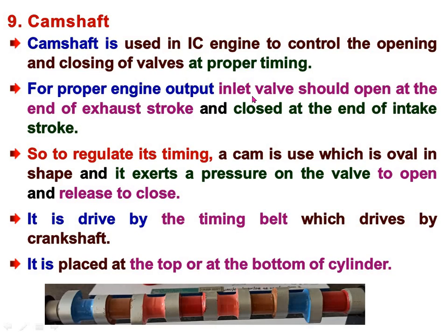For proper engine output, the inlet valve should open at the end of the exhaust stroke and close at the end of the intake stroke. It means for taking in fresh air, in the case of a four-stroke engine, or our diesel engine, at the start of the suction stroke, or at the end of the exhaust stroke, the inlet valve should remain open, and after the end of the intake stroke, or suction stroke, the inlet valve must be closed.